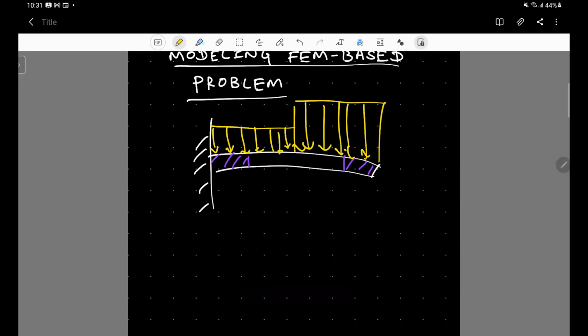Whenever there are drastic changes in the loading conditions, then at certain locations you need to capture these changes, you need to introduce nodes. And if there are changes in the material in such places, you have to be particularly interested in the mesh size as well as the nodes, and you use the proper elements at appropriate locations to tackle such problems.